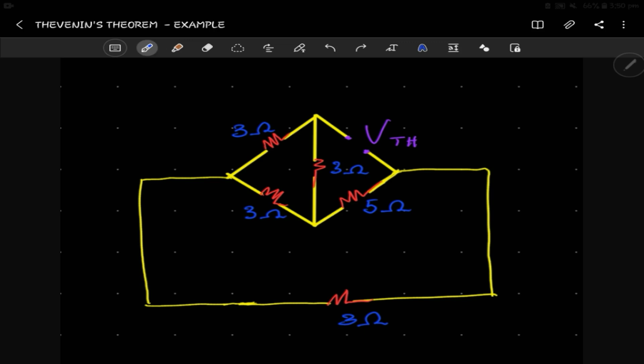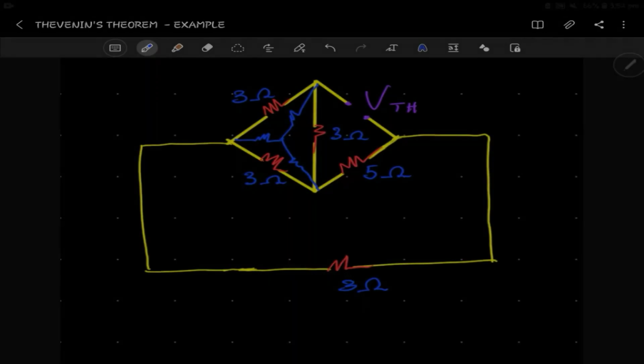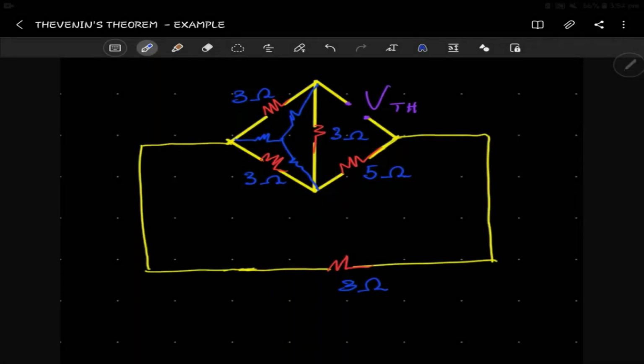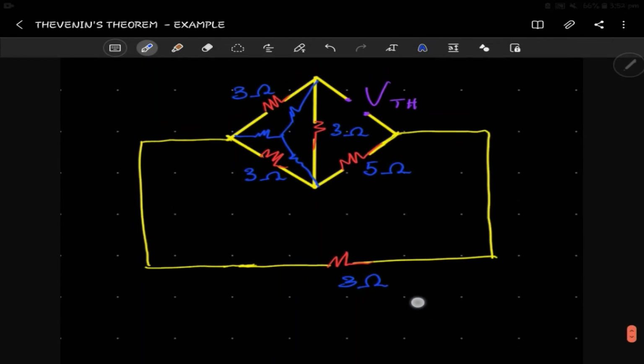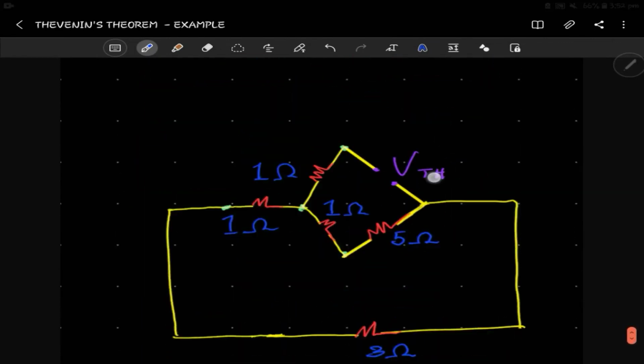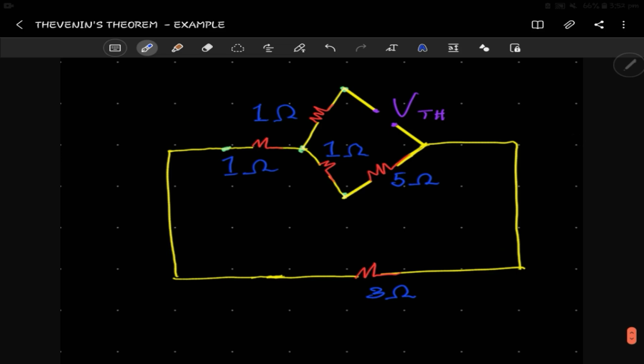So a way to do this is that we transform the delta to star, which gives us an equivalent resistance system in this way. So we introduce it like this, which is all simple. Then when we simplify that and remove the delta, we end up getting something like this. We are still in the simplification process, redrawing the circuit. At times, if you really understand it, you shouldn't need to redraw everything, because you'll be able to see what's actually happening.